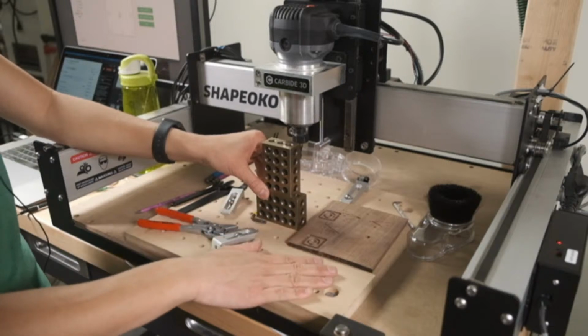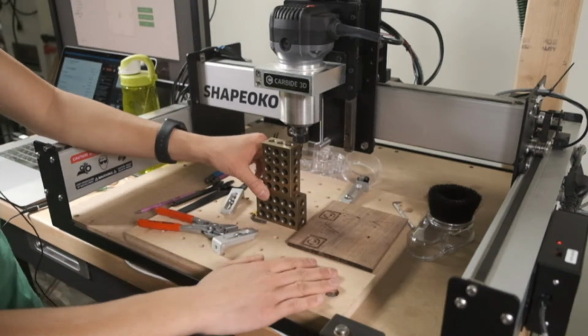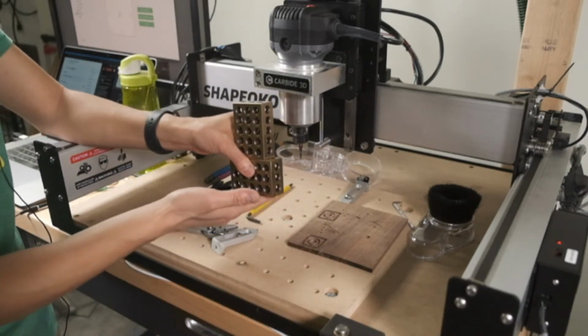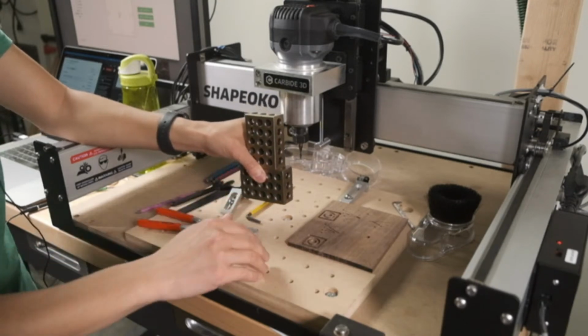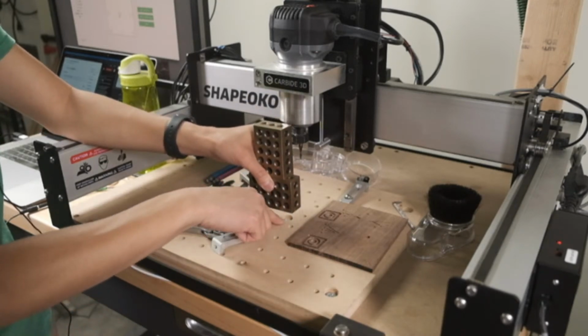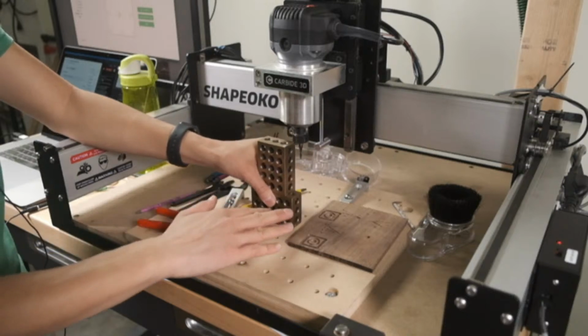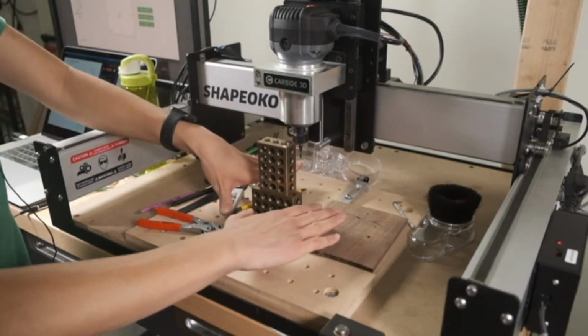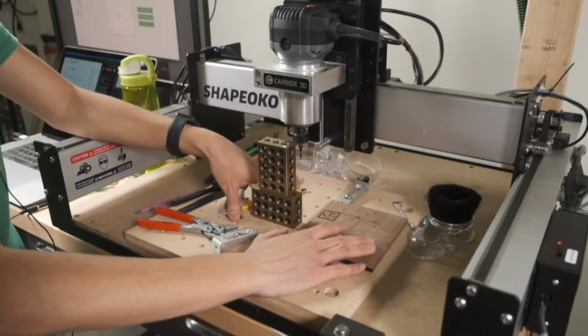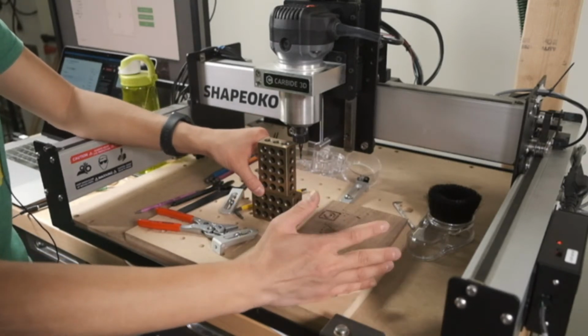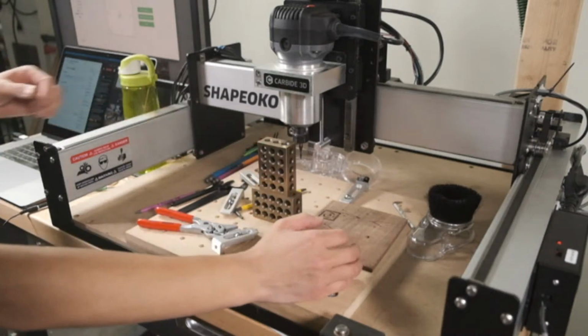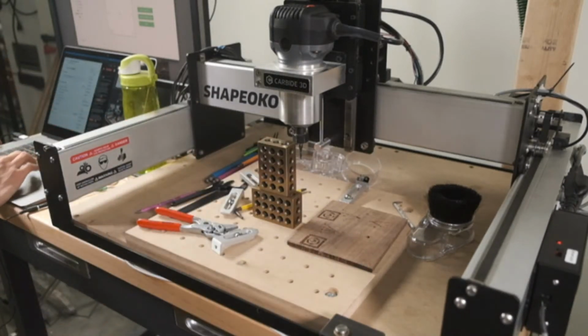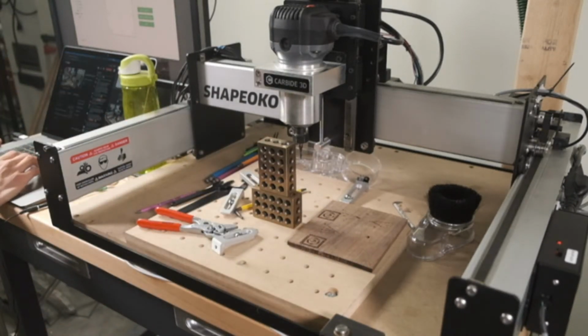You can surface your wasteboard first. If there are scallops, just make sure whatever block you have resting on it covers or spans multiple rows, so it averages out to be level. You could also get a flat piece of glass and put it on top and use that as a reference surface. A mirror will do just fine. So you've got options. All right, so that is more or less the basics of what I want to cover.